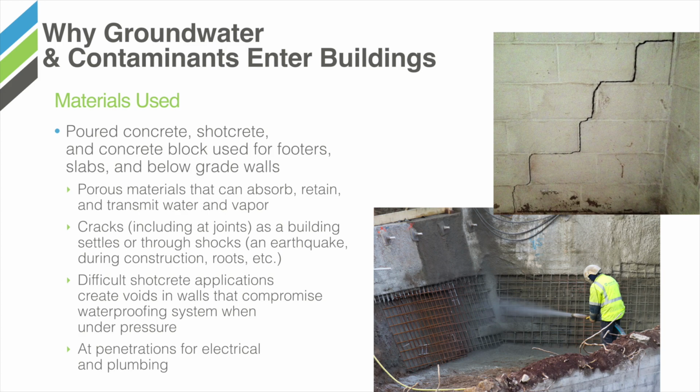Shotcrete creates a significant problem because of the unevenness or the shadows that are created during a shotcrete application. It is crucial that any membrane system have a sound substrate to support the product. The challenge with shotcrete is when the voids are created and hydrostatic pressure is present, it can create a significant amount of pressure on the membrane itself.